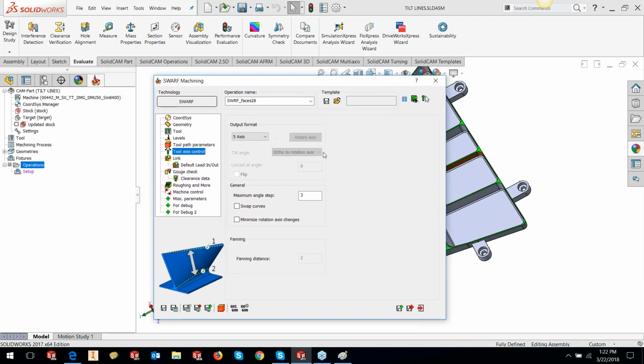In the tool axis, we have introduced one new functionality. We now have two outputs. You can get the output as 5-axis, or as 4-axis. Now, you'd ask me, where are you likely to use a 4-axis swathing? Just imagine a cylinder with a lot of pockets on it. Our wrap function, which we generally use in 2.5D, a similar part can be done using swathing